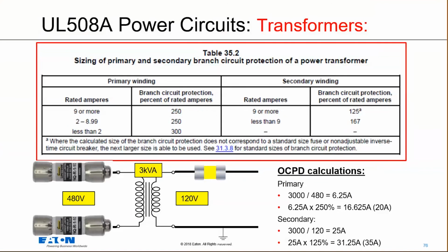So when you're talking about primary and secondary overcurrent protection, you can size a little bit higher. Maybe that's the case because I've certainly seen times where control transformers in particular are getting more and more efficient. You may see more and more current go through those as they fire up, so sometimes you may see a nuisance trip. So basically what you want is the most current limiting Class CC fuse out there, which is our FNQ series, FNQ-R. When you put that on the primary, it gives you the most time delay, and if you put in secondary protection, you can maybe put some larger fuses on that primary. Hopefully that makes sense. Pretty straightforward.